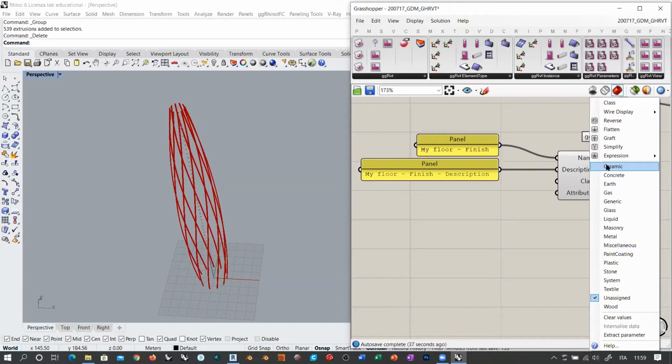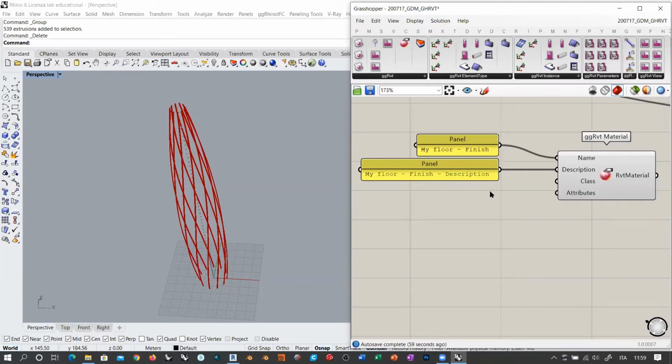leaving this information behind because, oh, I can edit this in Revit. It's a little more complex to go looking for the elements in Revit and change these particular properties. You must go back and forth inside the properties windows, and it's not that easy. So it's better to define this as soon as you define a material. So let's say we want to create a ceramic tiling floor finish.